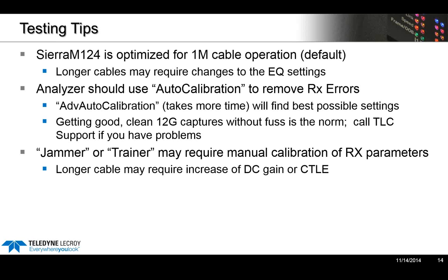Some testing tips. So Teledyne LeCroy, we have two 12G capable analyzers, the 2-port Sierra M12.2, the last 2 standing for the number of ports available, and the Sierra M12.4 or 124, which was our original 12G product, has 4 ports, and so it services all 4 links of a standard mini SAS HD connector.